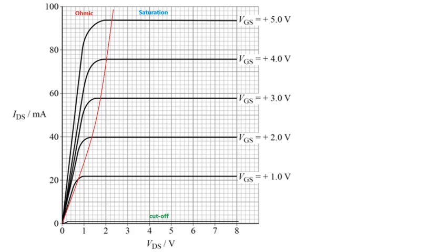Now, really, all we need to worry about is the fact that the transistor is either off, which is the cutoff region, or it's on and it is saturated. Yes, because we're only worried about this transistor as a switch. It's either on or off. So it's either the cutoff region or the saturation region. We're not bothered about the ohmic region. That's where you would use it as an amplifier. And we're not going to worry about MOSFETs as amplifiers. They're either on or they are off.